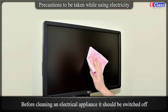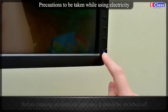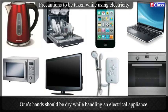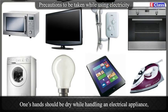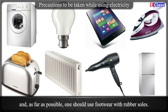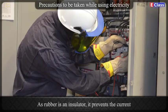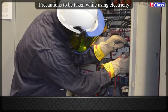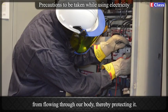2. Before cleaning an electrical appliance, it should be switched off and its plug removed from the socket. 3. One's hands should be dry while handling an electrical appliance and, as far as possible, one should use footwear with rubber soles. As rubber is an insulator, it prevents the current from flowing through our body, thereby protecting it.